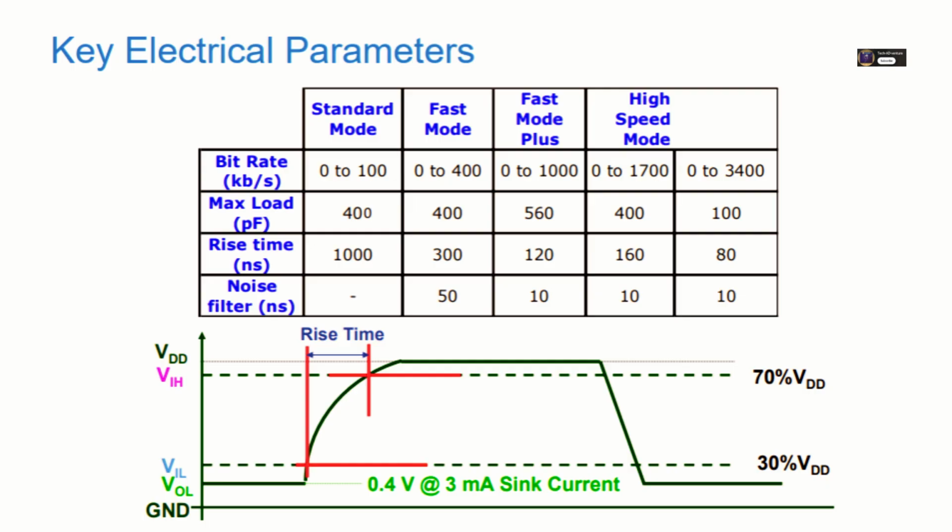They may be too complex for audio. There are, yeah. The I²C spec gives guidance. Essentially, the pull-up resistor needs to be strong enough, low enough resistance, to charge that bus capacitance quickly enough for the desired speed, but not so strong that it causes other problems. We don't need the exact formula here, but the principle is higher capacitance or higher speed requires a stronger pull-up,